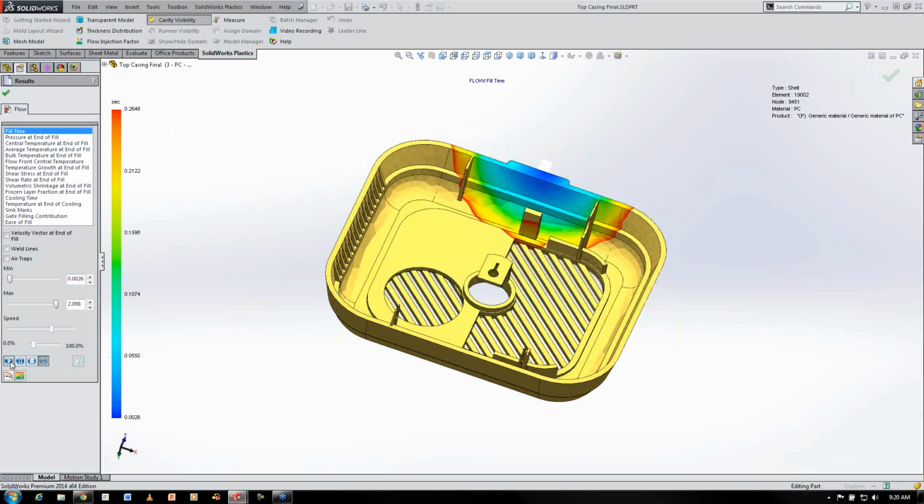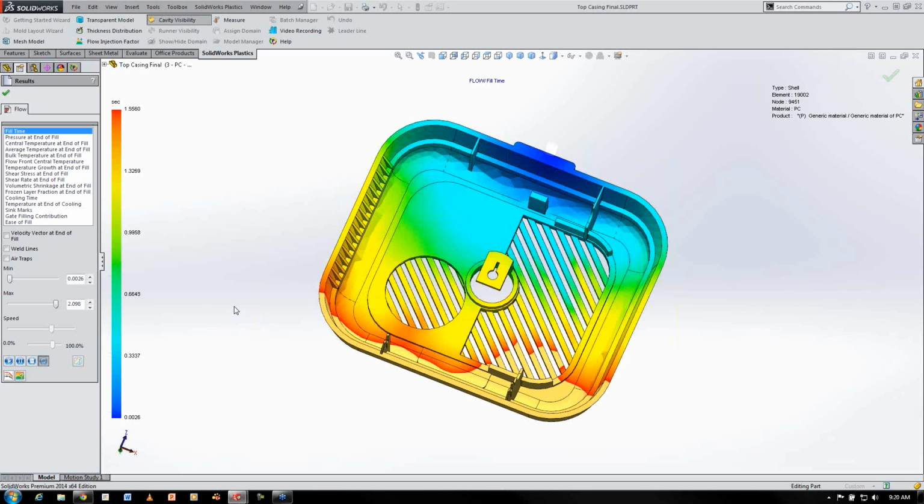Let's take a look at the fill animation. Shouldn't look overly different. We have a little bit more consistent behavior with the wall thicknesses around the outer edges of the part. It isn't racing ahead nearly as bad as the first example. It actually looks like things are coming together fairly uniform across the part. We still have some backfilling around this curved area. We pause it right about there. You can see we're going to have some backfilling in that lower, I'll say, corner of the thin ribs.